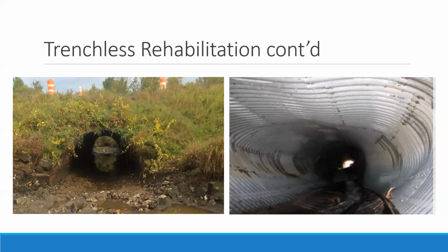And an important aspect of trenchless rehabilitation is addressing the structural issues that arise from the failing invert. So when a culvert loses its invert, there are two things that happen. First, bedding and backfill around and under the pipe is no longer supported and is allowed to enter the stream of water. The water would wash away any material that can be dislodged. Secondly, because part of the circumference or hoop is gone, the pipe is no longer able to retain the soil in the position as it was engineered.